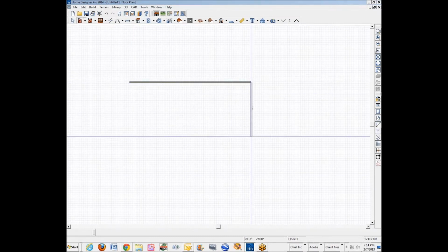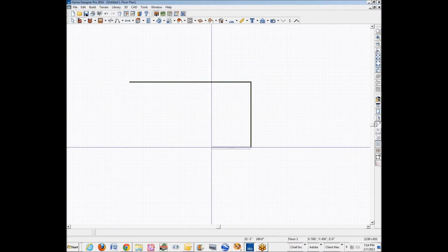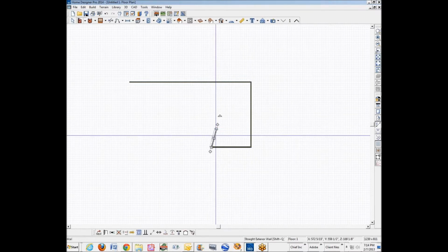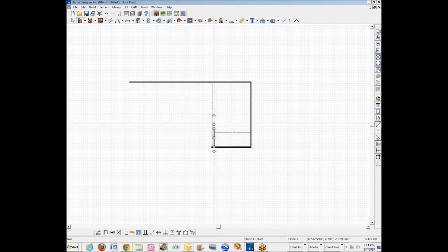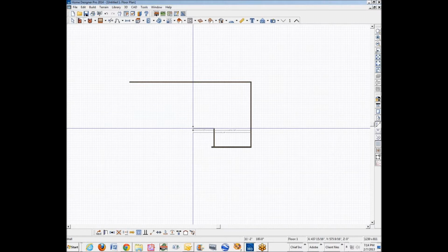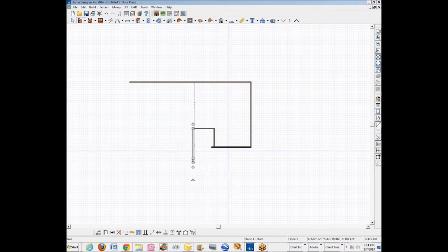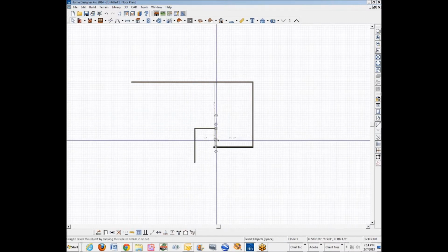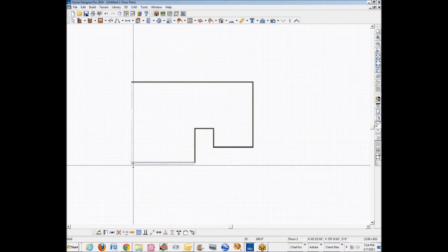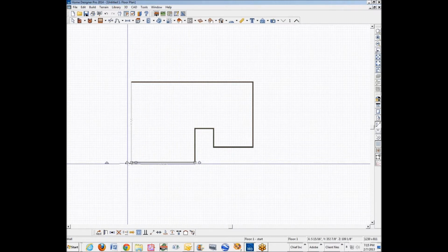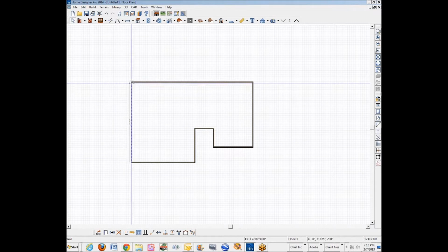See, now I'm drawing with the stucco walls that come around the front. Oops. Now I've got this extra handle here. You may not be aware of it. It's called Draw Same Wall Type. It gives you an extra little handle out there to, I'm going to move that over a little bit. That way it saves me some clicks and I don't have to go back to the wall and change the wall type and that sort of thing.